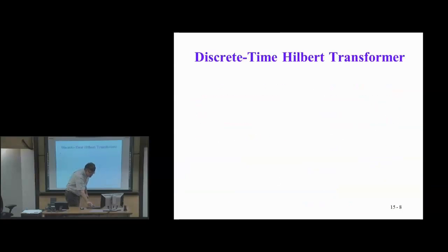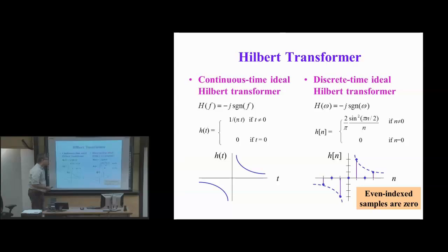So we're not going to derive this Fourier transform relationship. This is something you might do in another class, DSP theory, for example, on the discrete time ideal Hilbert transform. We're just going to use this from a lookup table. So if we look at the inverse Fourier transform, we know that this is our target frequency response from the previous slide. The impulse response is pretty strange. Now, it is odd symmetric about the midpoint. The midpoint's a bit odd because, otherwise, in the limit, from the left it goes to infinity, and from the right it goes to minus infinity, so we'll just call it 0.